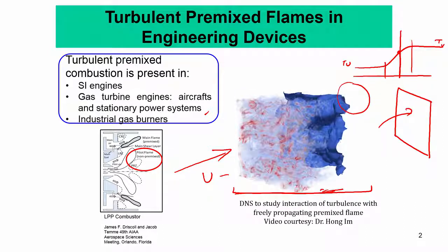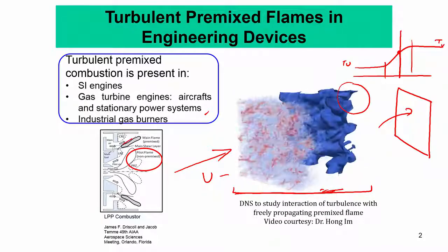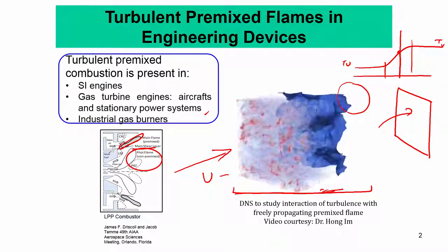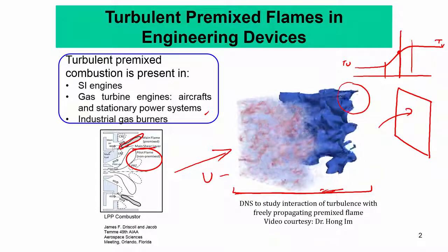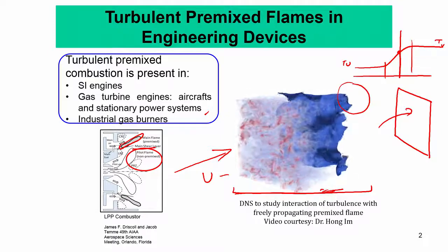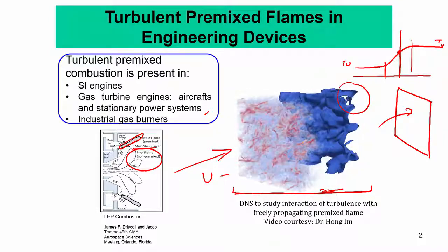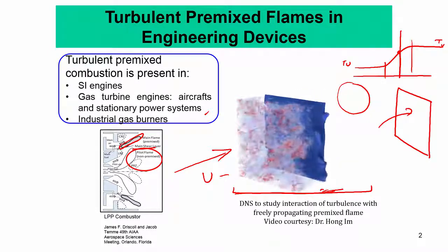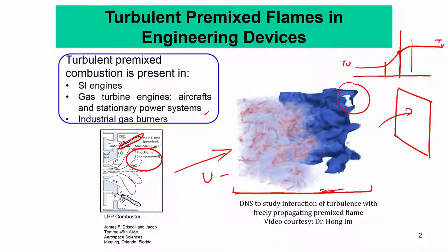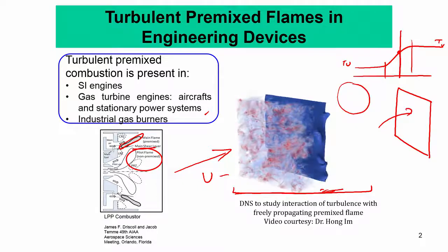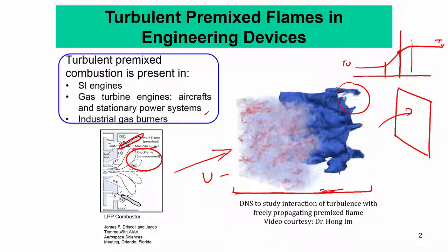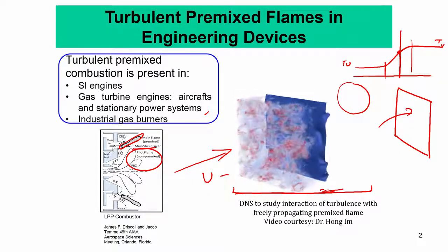Of course, in an engine, as you see here, this main flame branch is actually stabilized in the shear layers. Okay, in this main shear layer, as you see, it is stabilized in the shear layer. So, the presence of the shear also adds one more complexity to the flame structure. Okay, but nevertheless, this complex interaction between turbulence and flame is what determines the final heat release rate output from the engine, where the flame will be stabilized, if it can be ignited, and what the final temperature profile at the exit of the combustor will be. Okay, so many things emerge from this turbulence flame interaction.